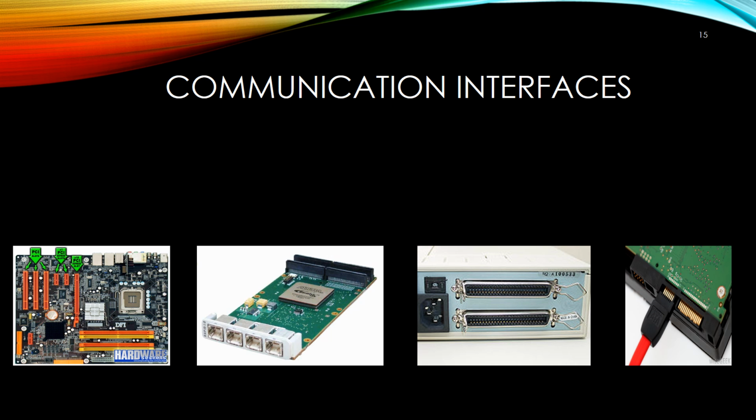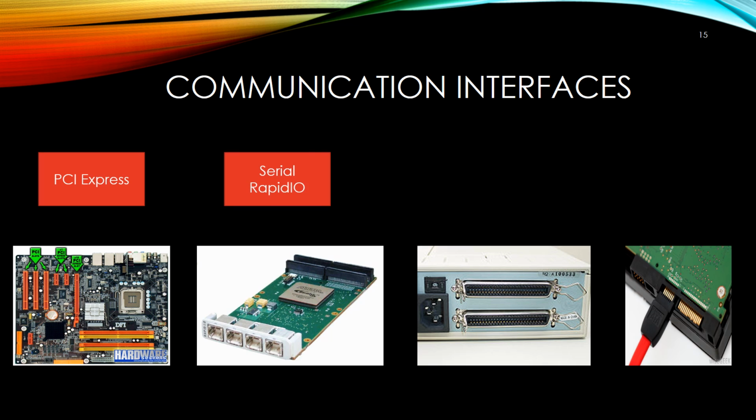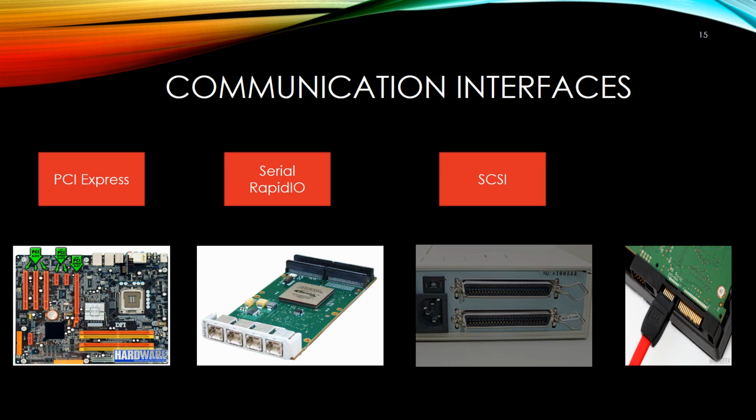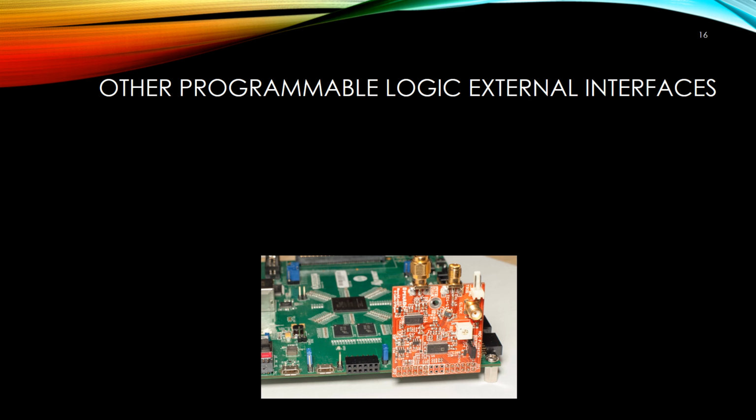Communication interfaces. Higher-specification Zynq devices usually include GTX transceivers, high-speed communication interface blocks which are embedded into the logic fabric. These are dedicated silicon blocks and are capable of supporting a number of standard interfaces including PCI Express, Serial RapidIO, SCSI, and SATA. The interfaces can be used to create connections to independent external devices such as networking equipment, hard disks, and further FPGAs or devices.